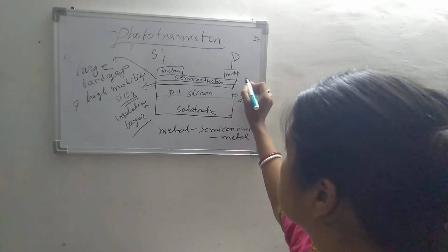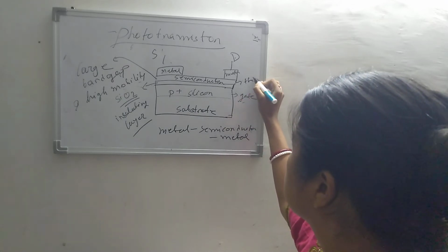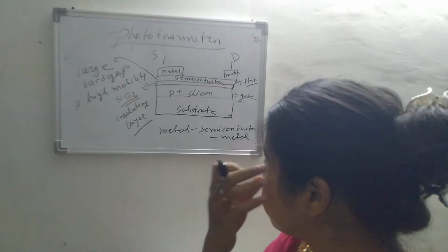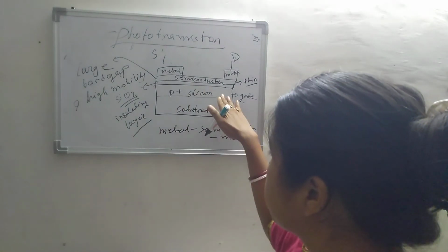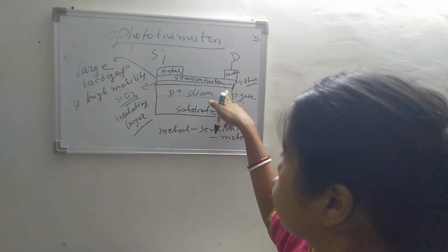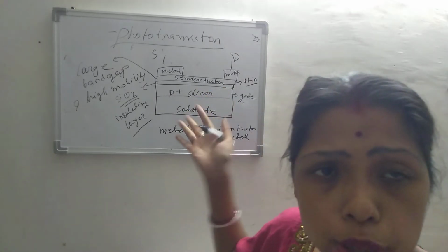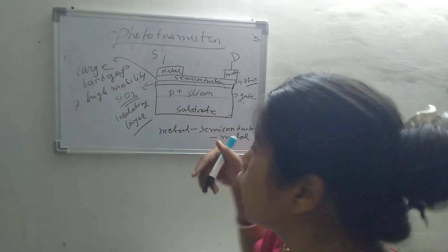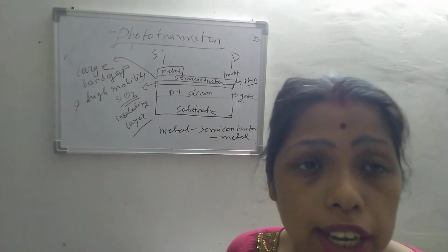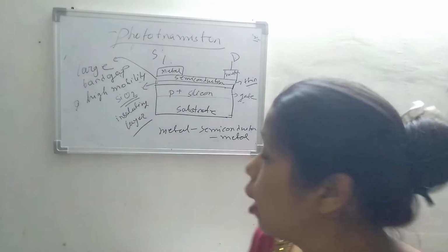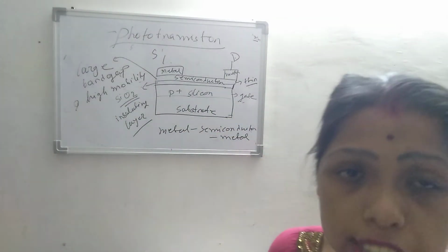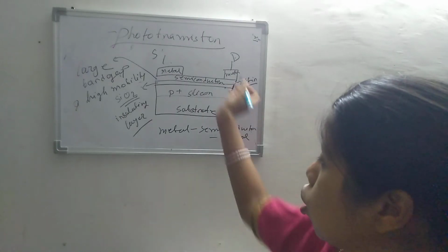And this should be a very thin layer. So, with p-type silicon, the silicon dioxide layer acting as an insulator, then the semiconductor, you can use various kinds of semiconductors. Then the two metallic layers are defined as the source and the drain terminal, like a metal-semiconductor-metal lateral structure.